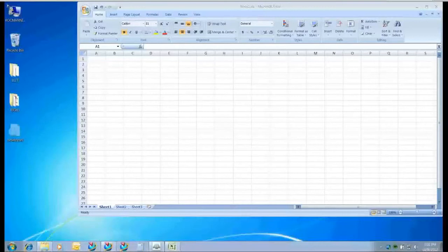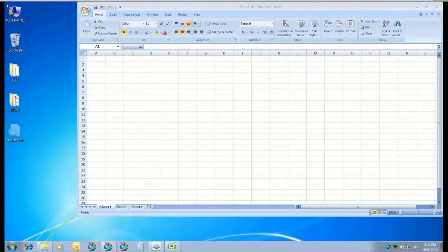Last time out, we had a discussion on how to install and use components in a CAM reuse library. In this short, brief demonstration, we're going to show you how to create a component and use it in your reuse library. First thing you need to know is that it is driven by Excel. This way we can manipulate the model easily enough just by changing a few variables in a dialog box. Your design intent, you need to know up front how you want the model to be designed, what your parameters are going to be called, and how you want to use those to manipulate.